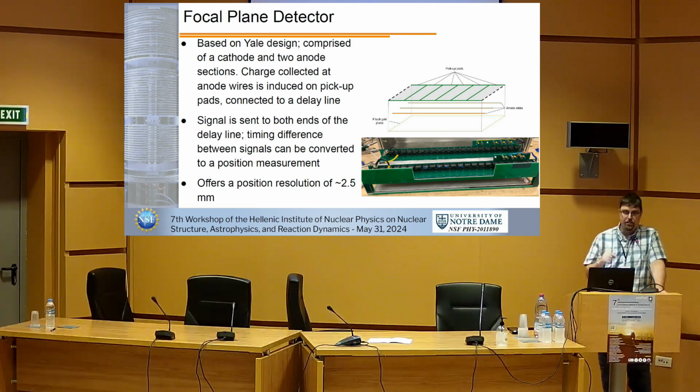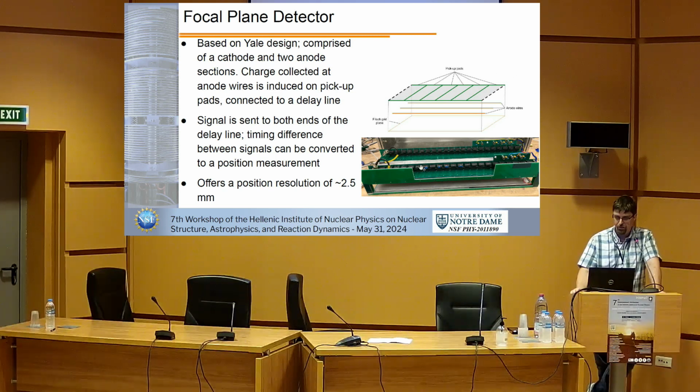Now, each of these pads is separated by a delay line circuit. So we can compare the induced charge on either end and the time between them to effectively get our position determination. And by using our new Mesytec digital DAC, we're able to get a position resolution of about 2.5 millimeters. And here you see a picture of the various delay line circuits.